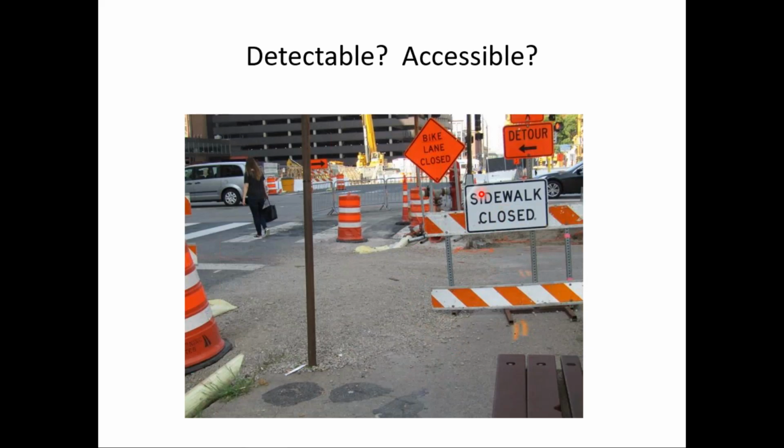No, it's not. Again, a blind pedestrian can't read that message. And if they're relying on their cane, I would argue they could find a path through here beyond that sign, which they can't see or detect. So this is not detectable. And if we look closely, you can see that this looked to be the main access route to the job site.